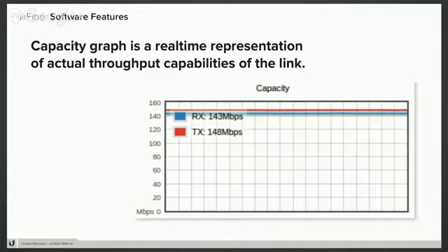And the radios on the far side, the receivers, are decoding that pattern along with the user data and determining exactly how much data they were able to receive. And so what that gives you is not just an estimate, but it actually tells you how much data was passed over the link at any given time. So by using this, you can take a look and very quickly determine how much bandwidth you have, and if the link has been degraded for some reason, maybe a tower fell over or some event that you didn't anticipate, you can see it right there all the time.